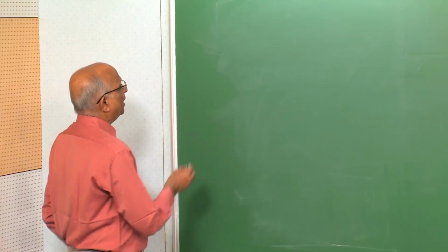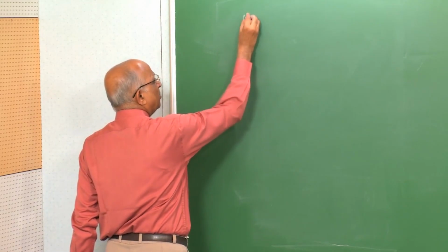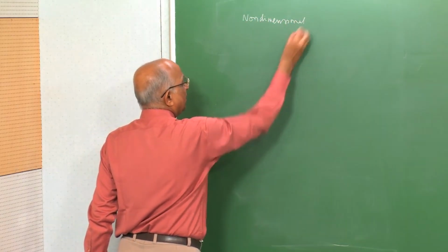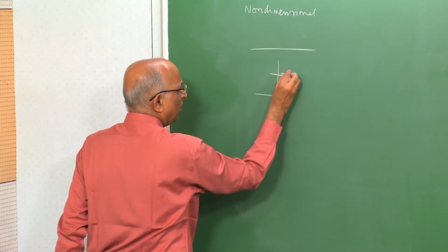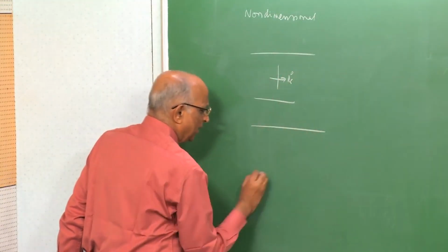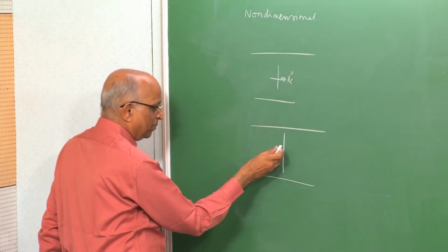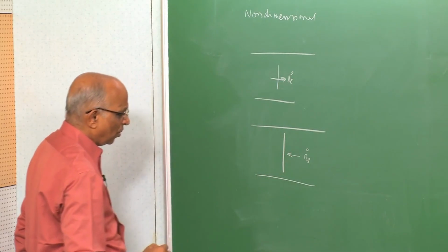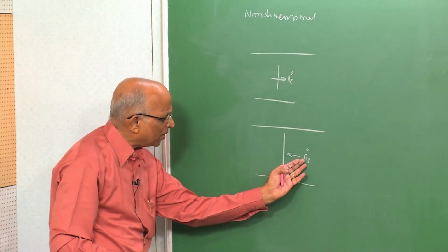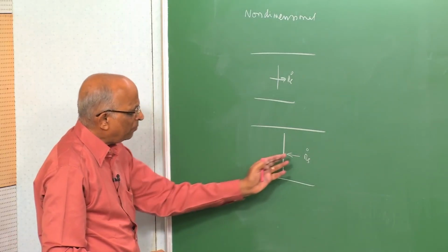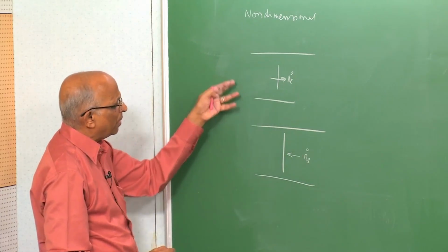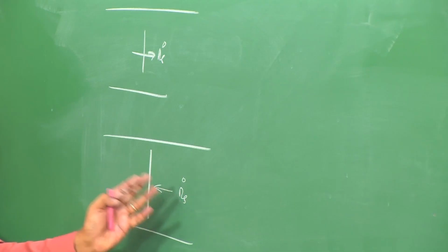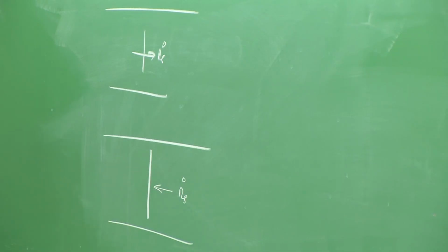To be able to do that, it is better to do it in a non-dimensional case. In other words, instead of writing that the shock progresses with a velocity Rs dot, or rather in the frame of reference where the shock is stationary, the gas is moving towards it with a velocity Rs dot. Instead of carrying the term Rs dot, can I non-dimensionalize it and put all the expressions in terms of P by P naught, so also do not carry the units of meter per second or kilometers per hour in the shock speed.